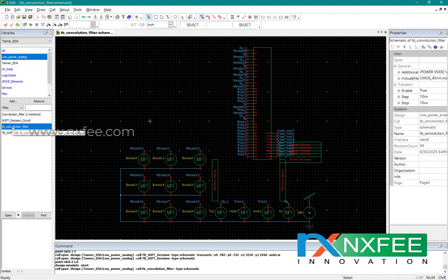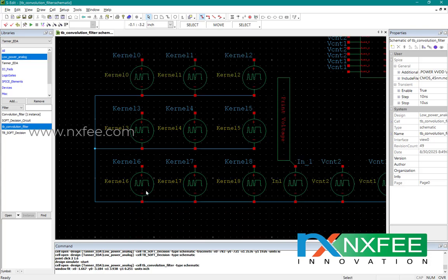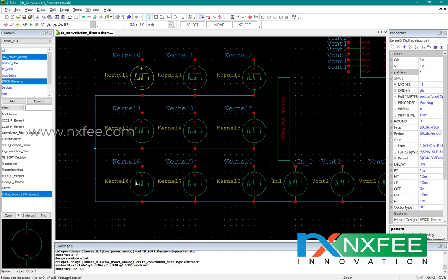Okay, that is the convolution part. This is the convolution multiplication of the kernel. Here we applied a 3 cross 3 kernel multiplication, that's why we gave kernel 0 to kernel 8, kernel 0 1 2 3 4 5 6 7 8. Here we applied the coefficients 101, 101 and 101. Using these kernel coefficients, we applied a multiplication model.